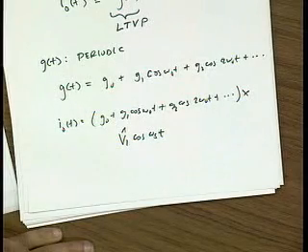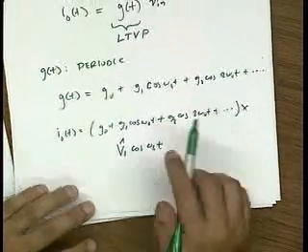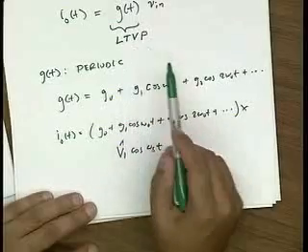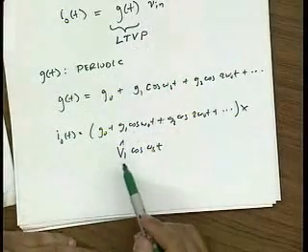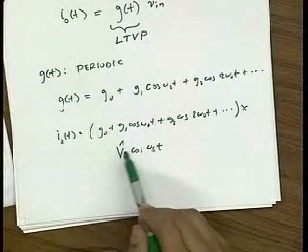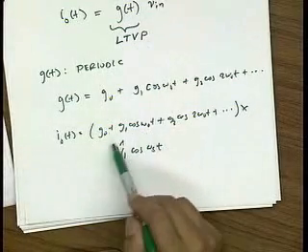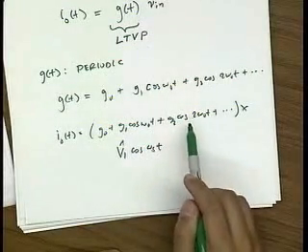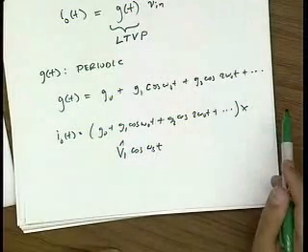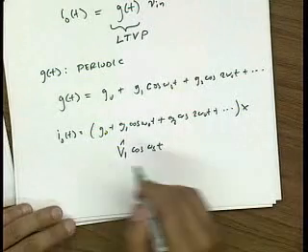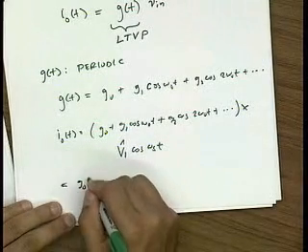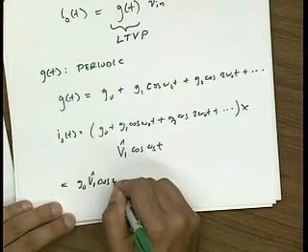So we see that the action of a linear time-varying periodic circuit is to take our input signal and multiply it by some DC term, and then multiply it by cosine omega, and then cosine 2 omega, and cosine 3 omega, and so on and so forth. So the output is G0 V1 cosine omega s t.